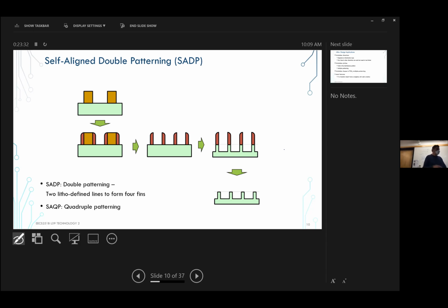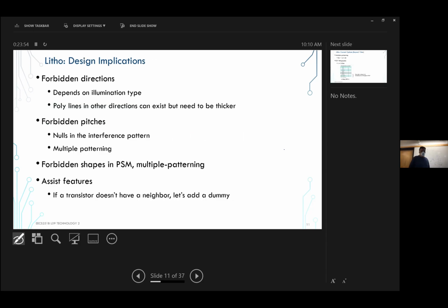There are a good number of papers published about that, and know-how in industry on how to get around it. But it can surprise you if you're doing something precision analog and you really care about controlling leakage paths. Watch out for these dummy transistors, or just stay away from it. Okay.